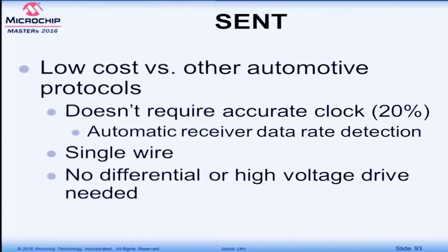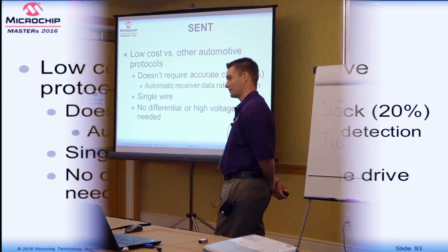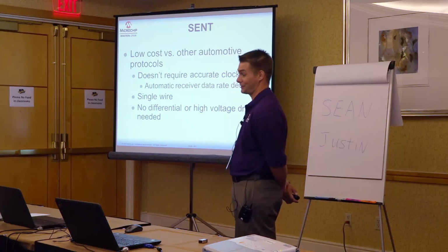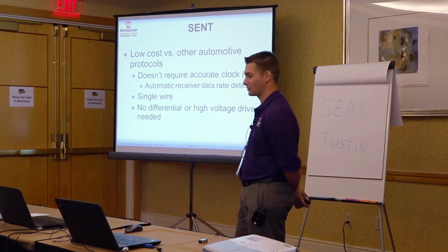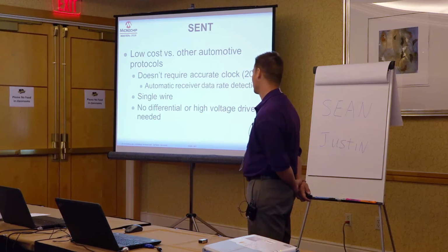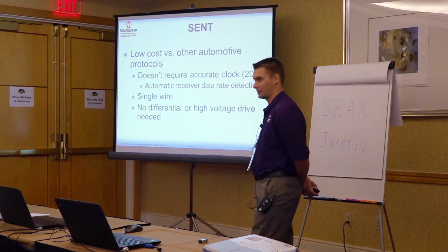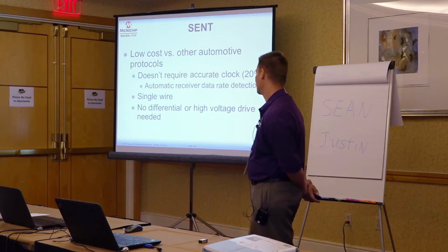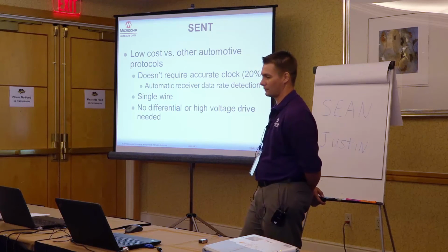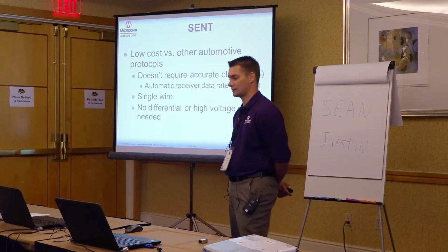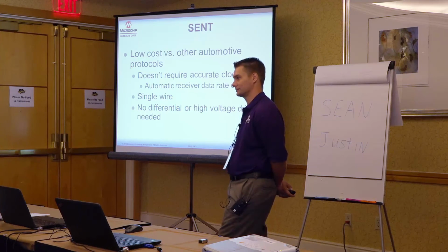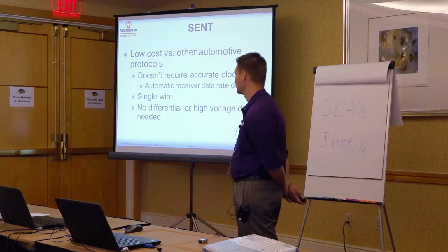What makes it lower cost? Well, one of the main things is that it doesn't require an accurate clock, so you probably don't need a crystal. You could use the internal oscillator, and it's hot under a car hood, so if that oscillator drifts 1 or 2% or 10, you're okay. It'll handle up to 20% drift. And that's done by how the receiver synchronizes it, which we'll get into a little bit later. The other benefit that it may have over another solution is that it doesn't need a differential or high voltage driver like some of the other ones do.